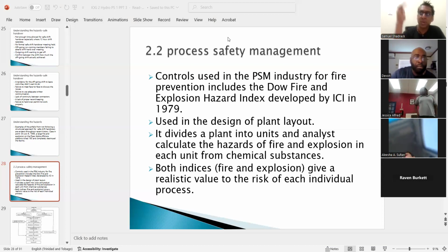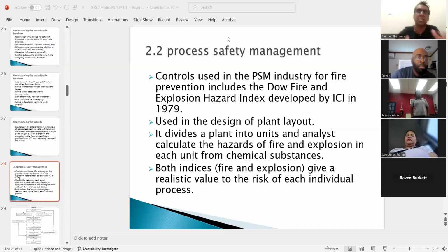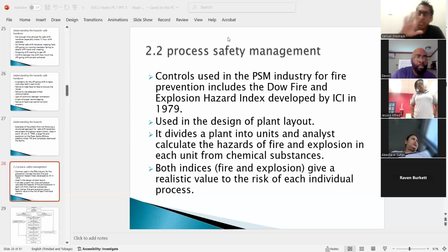A large work area is broken up into different areas, and like I said, we call it compartmentation, and then we see how to prevent fire from the warehouse from meeting the workshop, then from the workshop from getting into the office. Each area is treated as a unit. Each area is treated in such a way that it has fire protection built into it. So sprinkler systems, fire extinguishers, fireproof doors. What again? Maybe wall coating, fire resistant materials, metal materials so that the fire doesn't spread from one area to another area anyway, right?